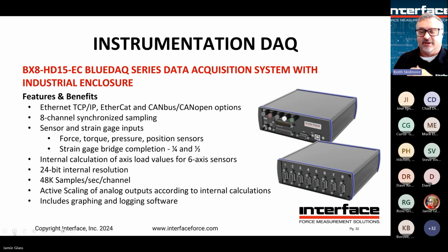If something's on a network and you want to use it over EtherCAT, it's nice to have the ability to actually configure it via its own software. And then the device on the network is just outputting data, or using basic commands over the network. Now, sure, there's lots of different commands available, but keep things simple, right? If you're just looking for data, you don't need to be able to program it over your network connection. So a lot of that is better done with PC software.